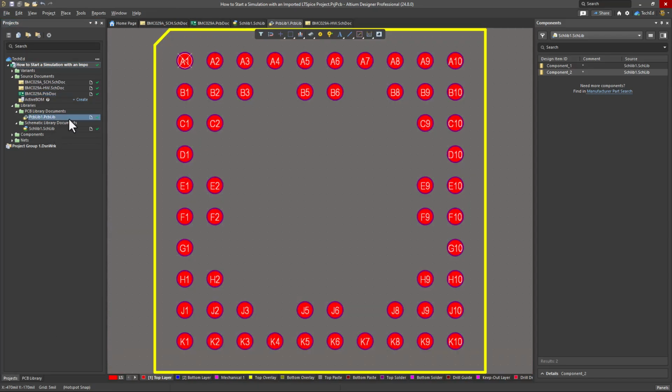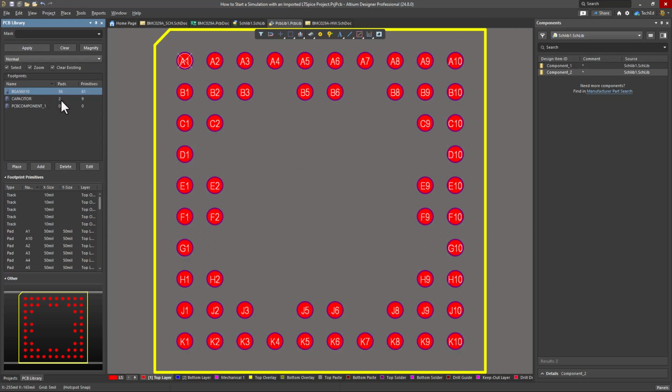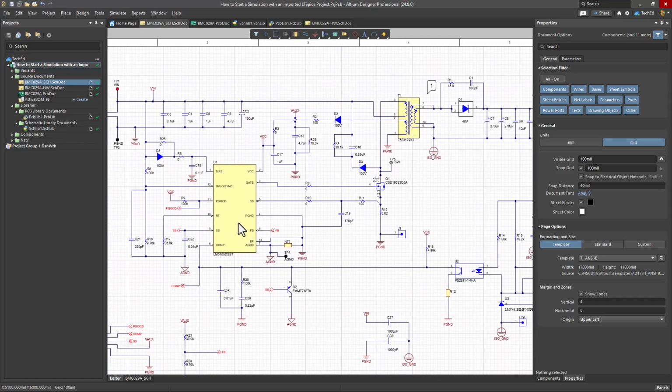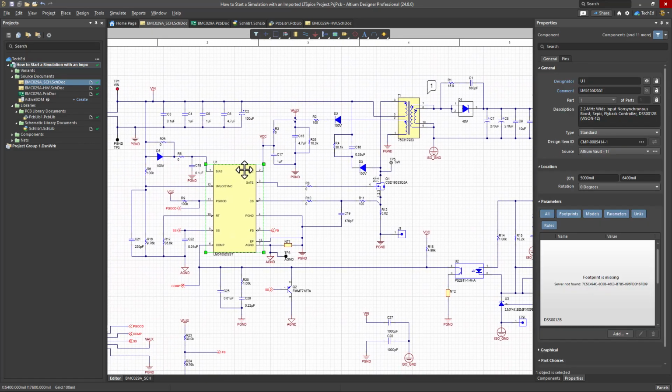What you do is, for the PCB footprints that are defined, you want these to be used by the schematic symbols. What's a schematic symbol? That's these things in the schematic document. These schematic symbols are the glue that connects everything, as far as instantiating a device or the concept of a device. And these are stored in their own file called the SchLib, or schematic library.